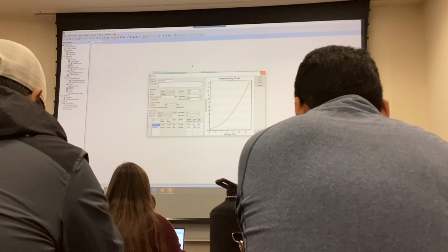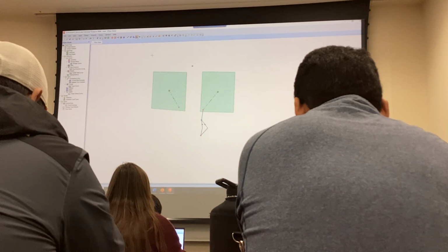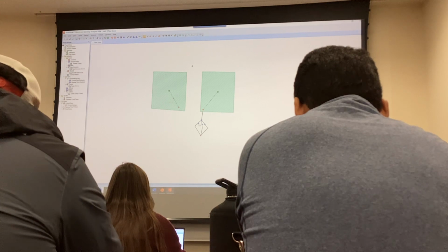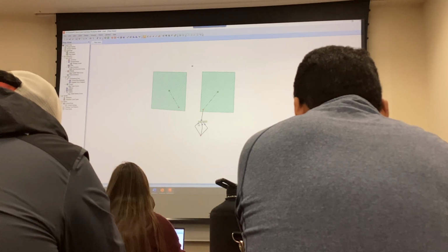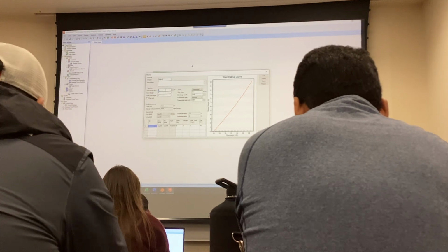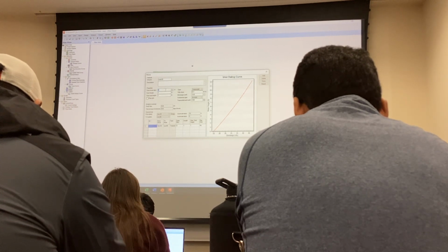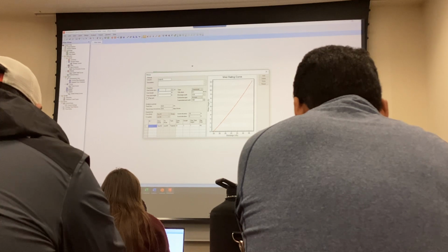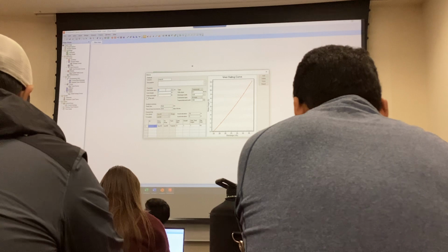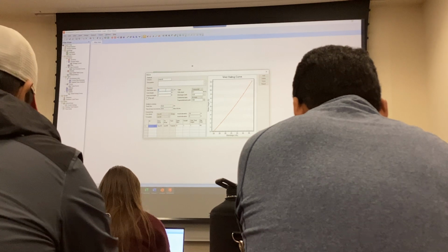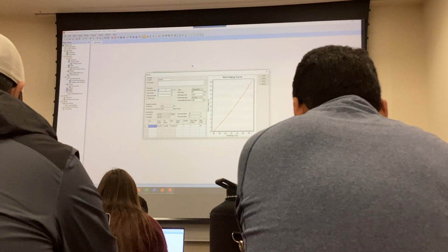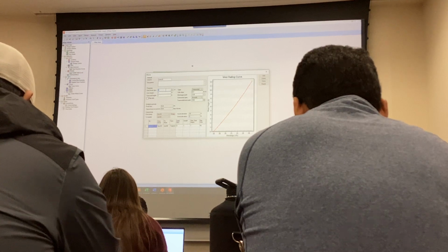Okay? Now, I'm going to put a weir here just to show you what type of information you're going to need for your weir. I still have 4 more minutes. So the crest inlet elevation. So the weir is specified. This part here is the crest of the weir, right? Where you measure your head. So that needs to be below or contained within that elevation for your detention basin. So make sure you have that.